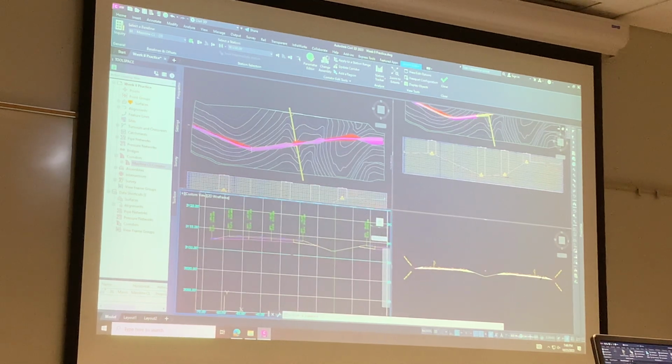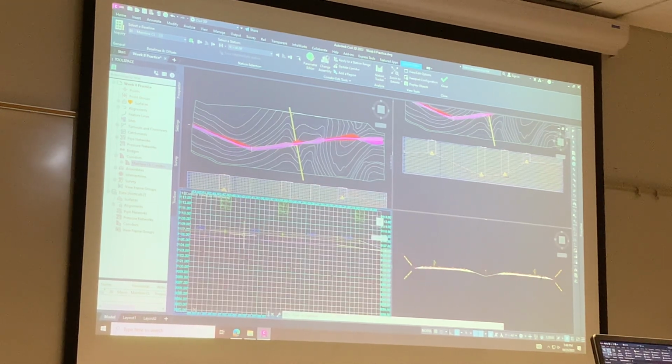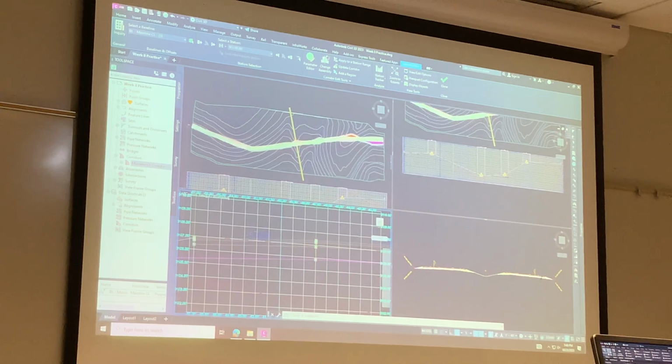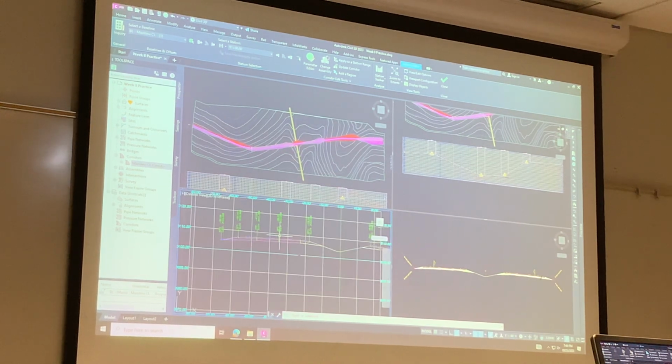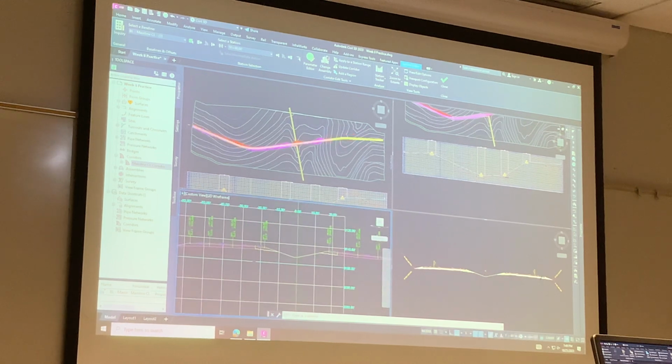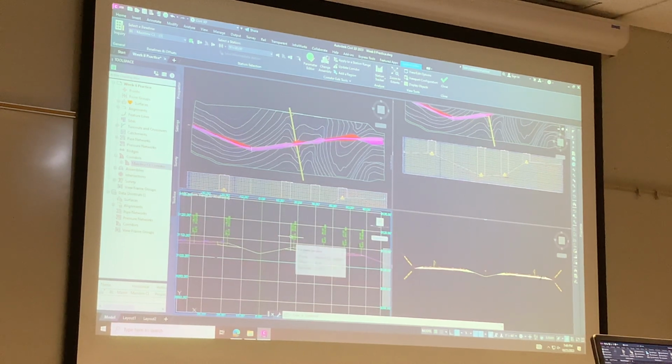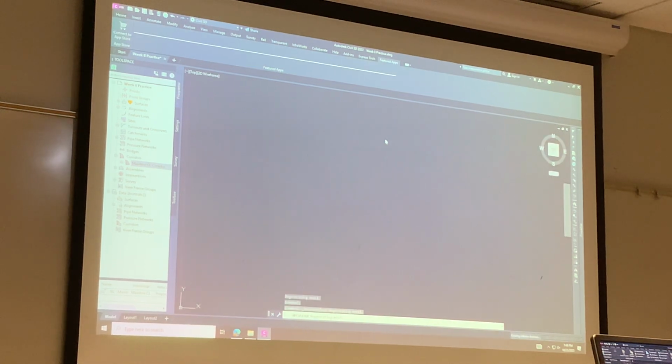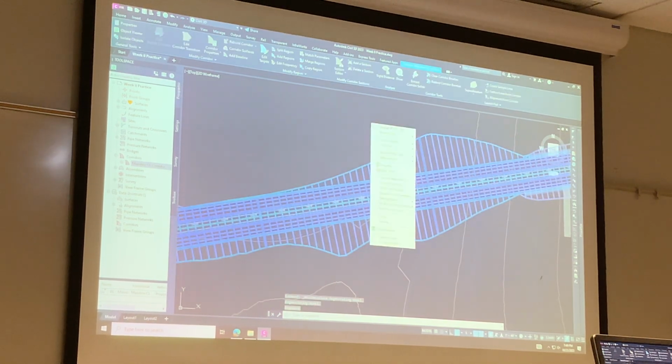Although I'm seeing this, there's also an issue with this one too. Oh. It didn't happen last week. If you select the corridor, right click, and then expand the, what is it, edit corridor properties or something like that here. Select it, right click, modify corridor sections, there we go. Modify corridor sections and then corridor section editor.